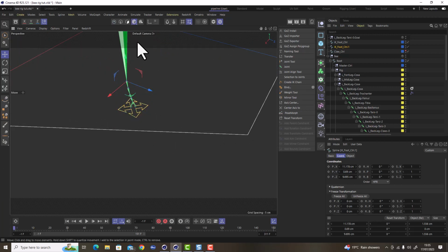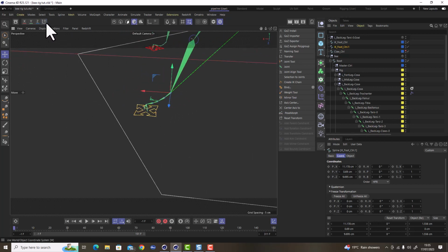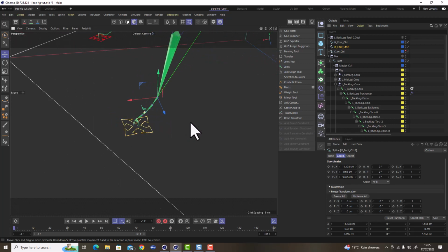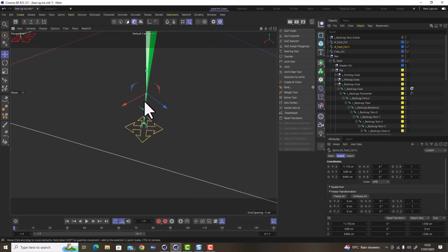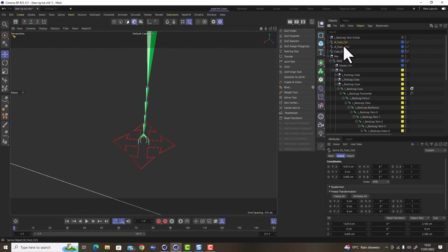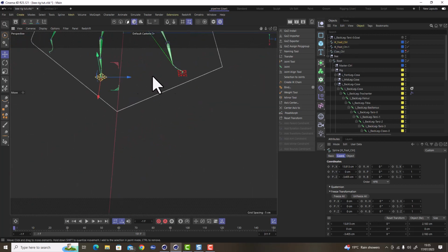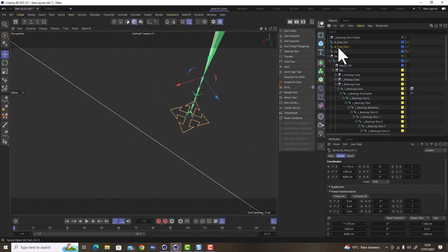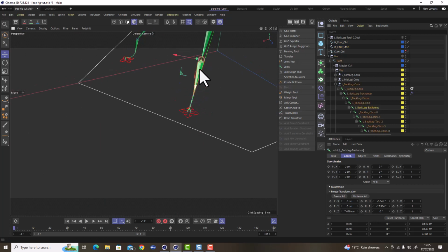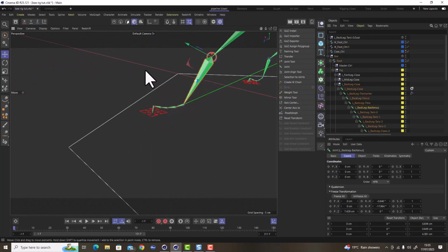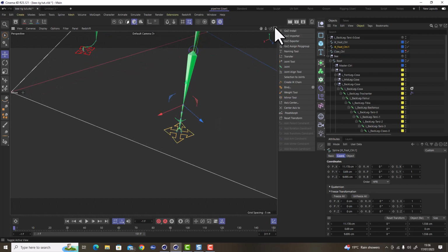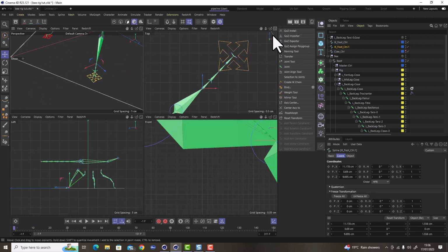is great. Now this controller is only going to be a controller that we literally lift up and down and kind of move it forwards and backwards, but you can clearly see that the controller is actually misaligned according to the joints. Now the other one, you can see that's aligned up really nice for us, but this one not so, as you can see there. If we select our joint, you can see here that that's lined up perfectly with that. So it's really down to the fact that we just need this controller to be lined up better for us. So what I'm going to do is I'm going to align that up right now.